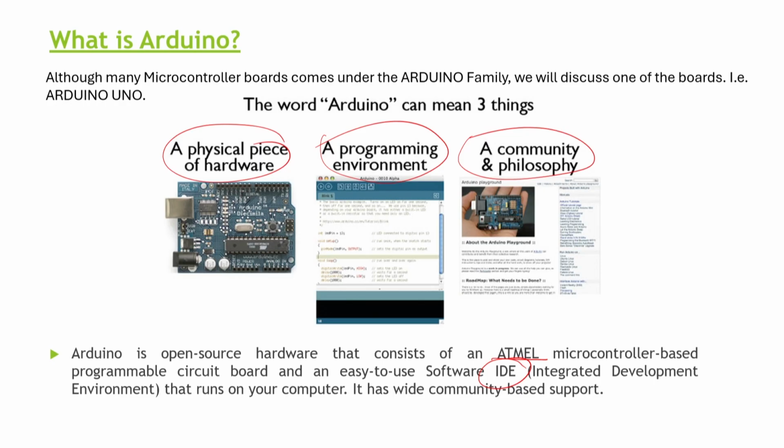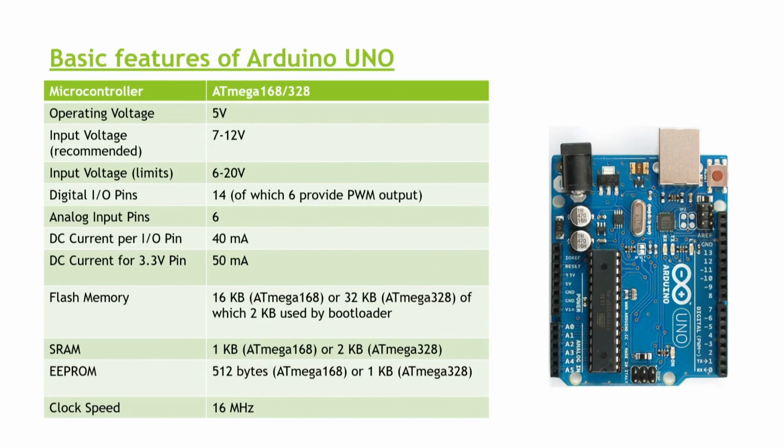These two things together can create very easily some of the simplest Arduinos or microcontrollers. A basic feature of an Arduino Uno is that its operating voltage will be about 5 volts. So, you do not need a very large voltage. Its input voltage can vary between 7 to 12 volts, and it can regulate the input voltage, but we have to take care that the voltage is not higher than this, or it will burn the Arduino.